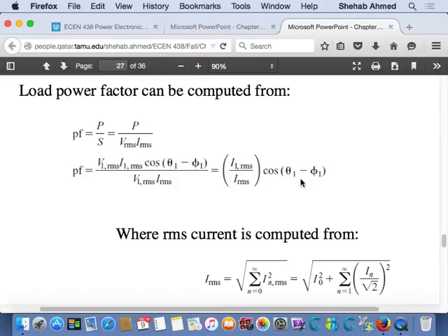And because of the poor power factor, all of this current is flowing in the utility's cables to transfer power to you, but they're not being paid for it. Because it's either harmonics or reactive power, and they don't charge residential consumers for this.